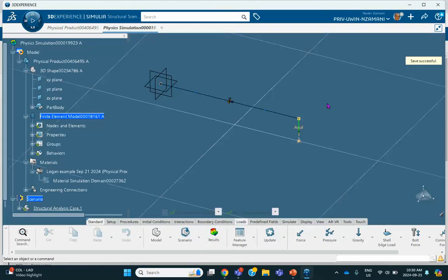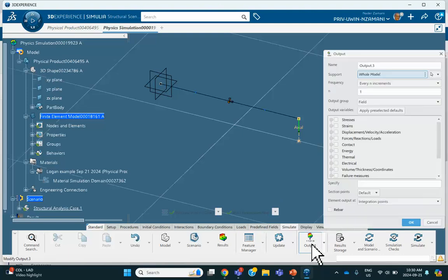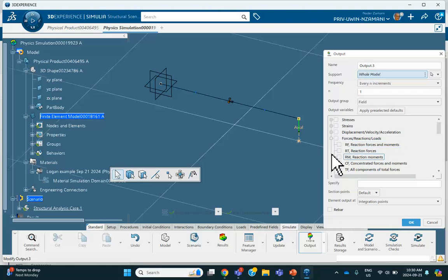Okay, good. So we go to simulate. If you want bending moment, shear force diagram, and things like that that were discussed in an earlier tutorial, you go to output displacement. Actually, I don't want to draw those things, but at least I want to get the reactions and things like that. You click on the force. There are some default ones, but these have to be requested. N force, nodal force, nodal force reactions has to be asked for. Otherwise, there are certain things that you can't get.